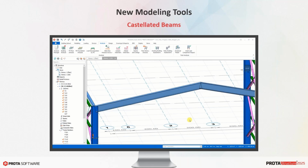Castellated beams are widely preferred for their efficiency. You can increase the depth of a standard I-beam by simply cutting the web and putting the pieces on top of each other. Or sometimes you just want to perforate the web to enable piping.